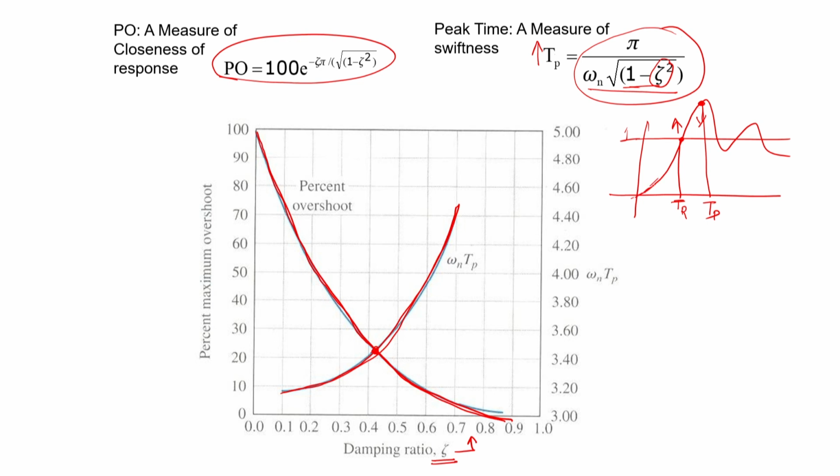would see that the overshoot will improve. So, it will come like this, like this, like this, and then come down. So, you can see the overshoot has come down from this point to this point, but the peak time has also increased. This is a problem which tells us that there must be a point of compromise between the two, between the peak time and the percentage overshoot. So, we have to choose the damping ratio such that both of them get satisfied in the system.